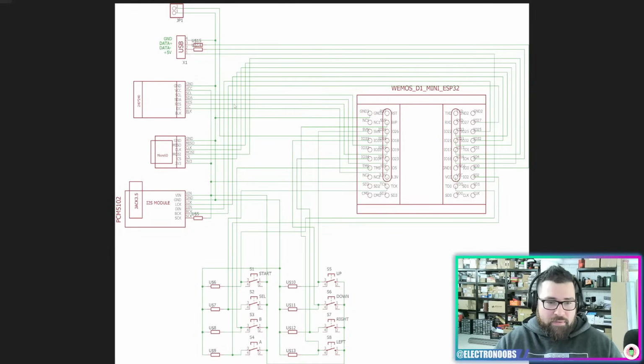And at the same time, if you want to just follow a track, for example this one here, if you want to see where it was connected, you just follow it like this with your mouse, and when you get here, I'm not even sure if it was this one and this one, because I already got lost. Imagine here where you have like, I don't know, 10 tracks. So never do this. I mean, it's a good schematic, but as you can see, it's very difficult to follow, and that's why we use the net ports or the symbols.